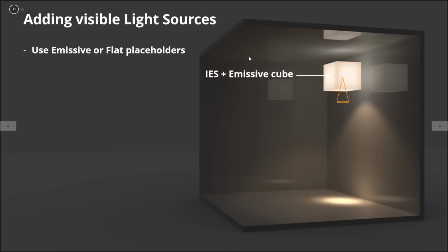You can also kind of layer lights, and I haven't messed with this too much, but it is a really interesting concept. I just actually tested this for the first time, and I was like, oh, that looks slick. I got two pieces of geometry. One was an IES profile, and then I put a little cube on top of it, and I made that cube emissive. And I used an occlusion texture, so one of our advanced textures, to give it the kind of darker edges.